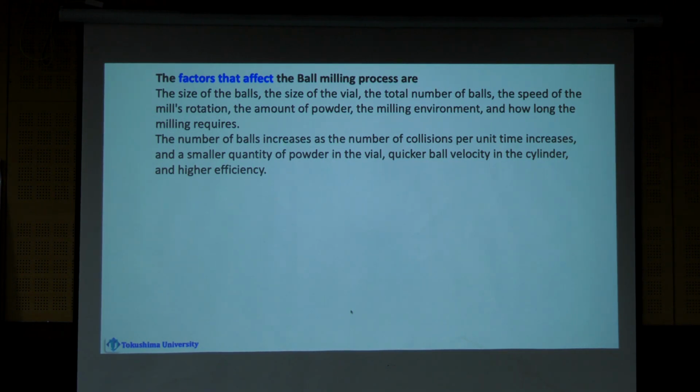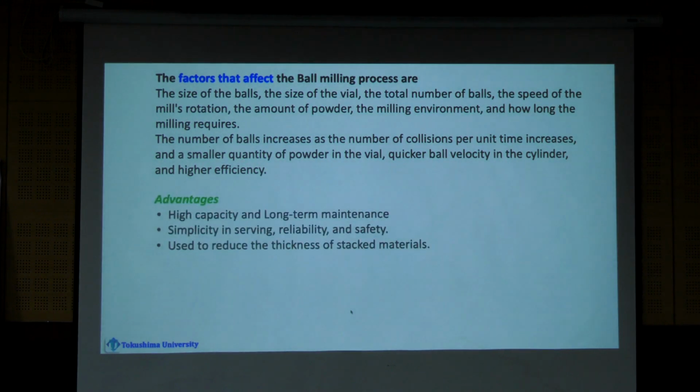If you increase the balls, the probability of hitting the bulk material becomes high. The number of collisions also increases, and a smaller quantity of powder in the air can quickly reduce into the smaller size, and you can get higher efficiency.